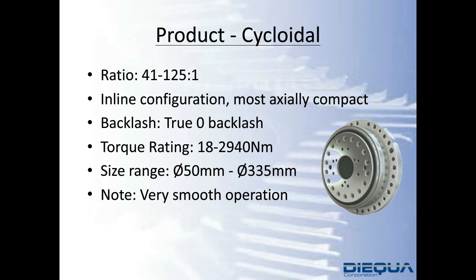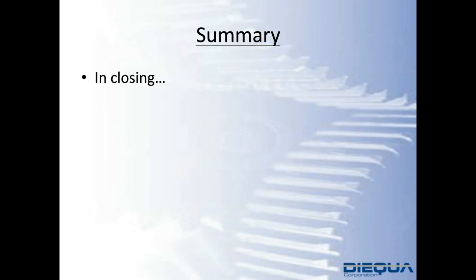So we've touched on 4 gear technologies, all of which offer a robot flange output. The benefit of the output being a robot flange facilitates a positive connection that won't allow for fretting, and gives you bearing support for those high radial and axial applications that have high tilting requirements, right? And so by going with the robot flange through one of these various gear technologies, you're able to better design your machine and give you a more compact design, right?